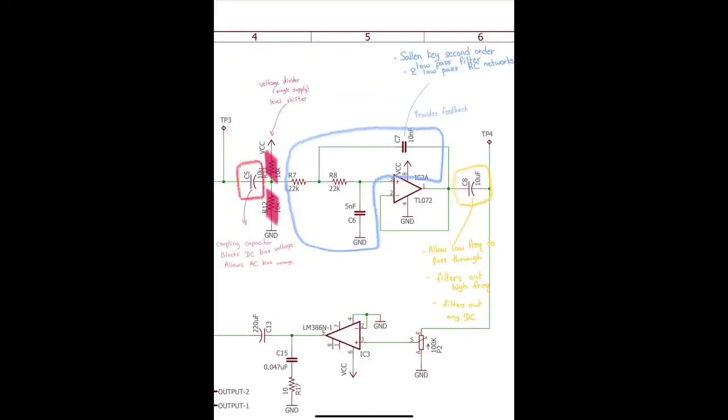Now for stage 3, before input is delivered to the op-amp, it first goes through capacitor C5. It lets the heartbeat signal through but blocks unwanted DC voltage, ensuring a clean centered signal is sent for filtering. Then the signal passes through a voltage divider of resistors R11 and R12, which also serve a secondary purpose as a level shifter to prevent clipping of the output. The output is then sent to IC2A.